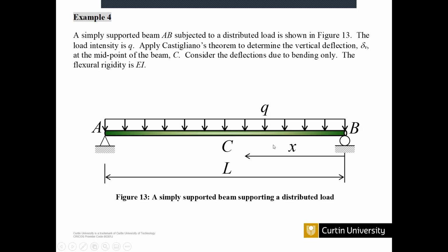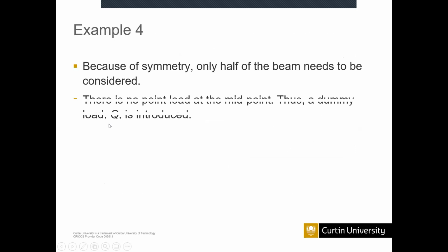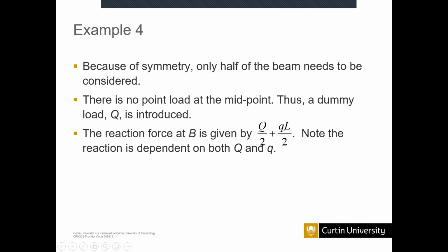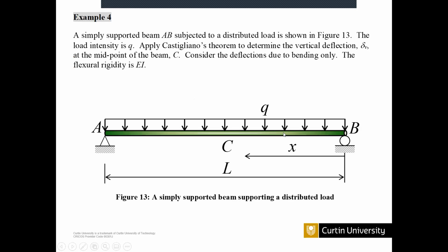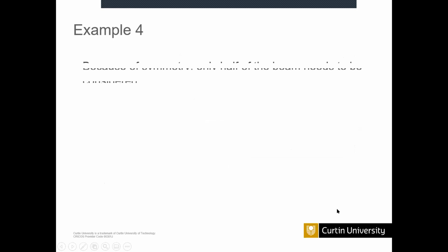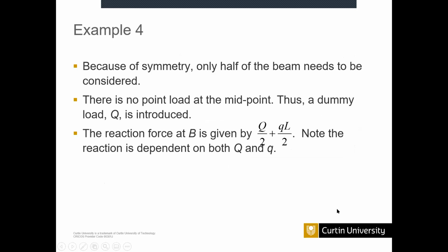Okay. So if it is a Q, Qx, this Qx divided by 2, the half of, and this is Q divided by 2 and Q divided by 2. That is the reaction. This x means L, no? Total length L, so QL divided by 2. So I think it's clear. The reactions at point A and B have the same values.